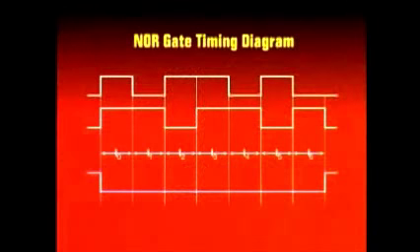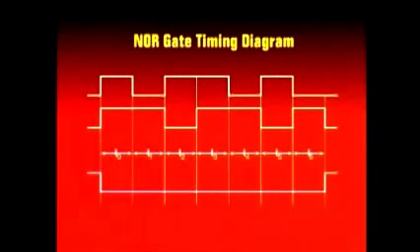Let's have a look at the timing diagram. Again, let's suppose we have a 2 input NOR gate having inputs A and B and of course the output F. We apply a certain number of inputs at input A and B. Let's observe the output through a timing diagram. A sequence of 1s and 0s is applied at the 2 inputs of the NOR gate A and B as shown in the diagram. The output of the NOR gate for intervals T0 to T6 is shown to be 0.